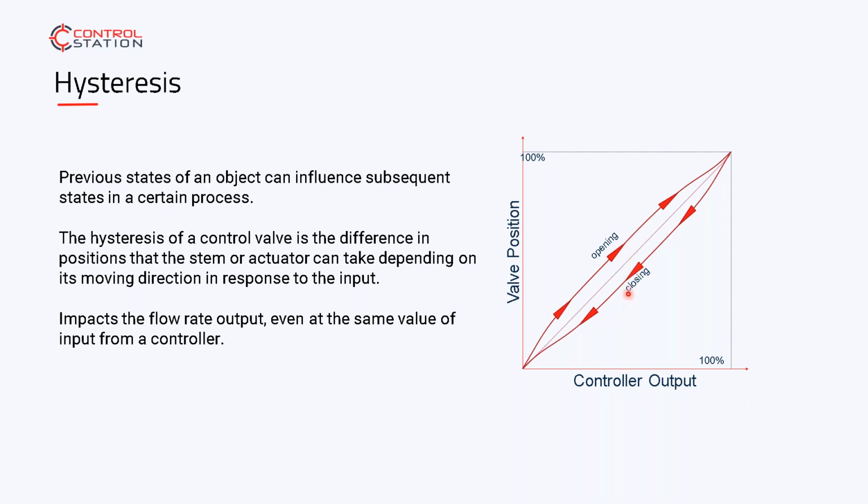So it's going to have those different conditions based on the same valve position, is the effect of it. Now, if we look back at the two slides that I just talked about, it can exhibit very similar characteristics to stiction and to deadband. So it's understanding your mechanical processes before you start to look at your processes, I suppose. A very good tip and trick that I would recommend is stand beside your piece of equipment and understand when the control system changes, you know, and I've done it across a radio on a number of occasions.